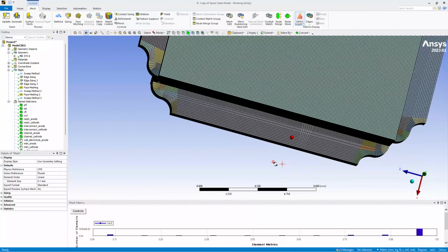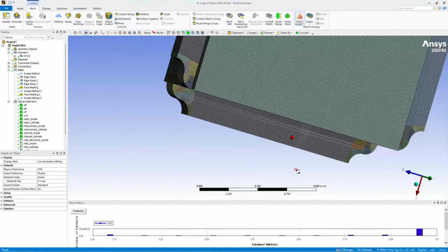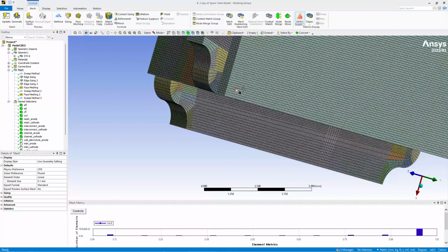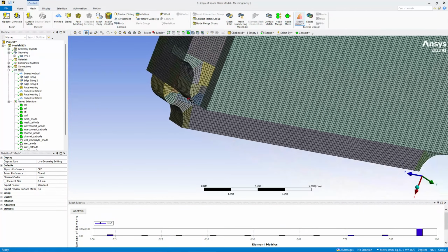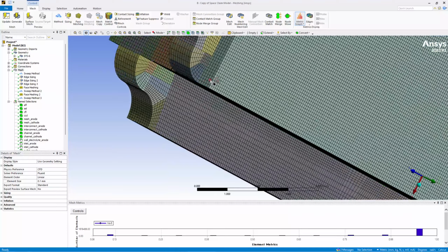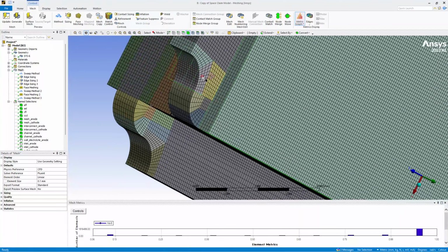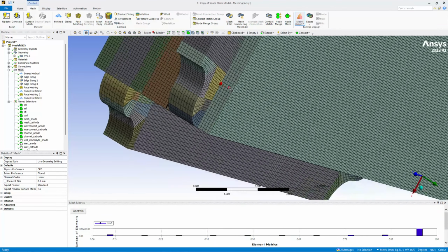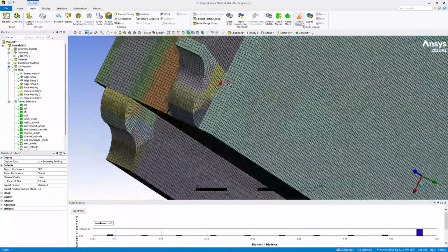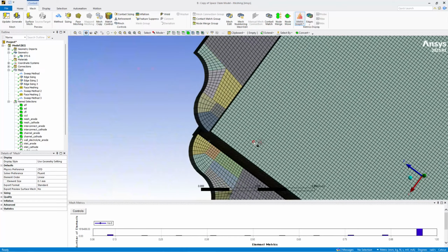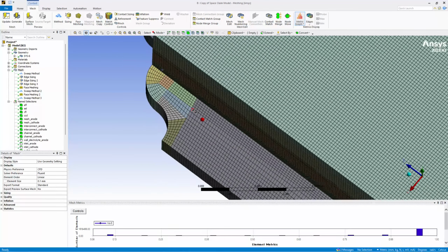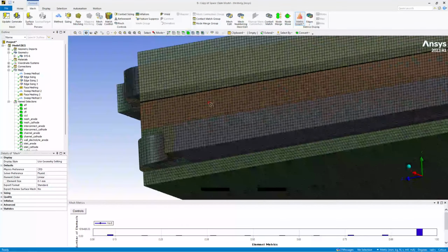This is bad. At the location where we had fewer divisions, a much better mesh is obtained, but higher, unnecessary divisions made it worse.